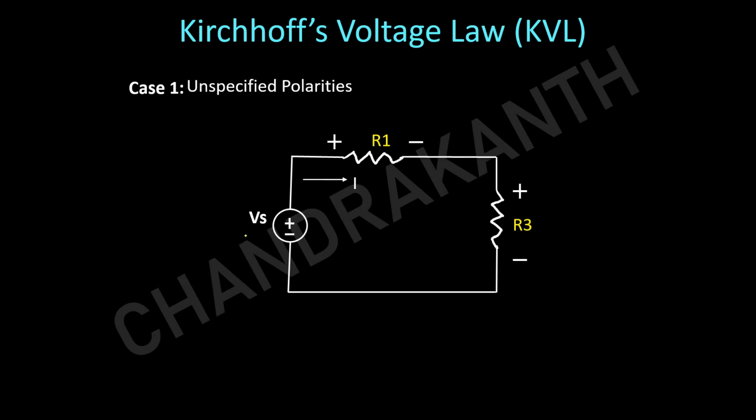So here the source voltage is given, so we don't have any problem. But here we don't know the voltage. Here also we don't know the voltage. So first we need to find out the voltage across these passive branches. For that, again we will take the help of Ohm's law, that is voltage equal to current into resistance. If you know the current flowing through this circuit, then you can multiply that current with the corresponding resistance value. Then we can get the voltage across that particular element.